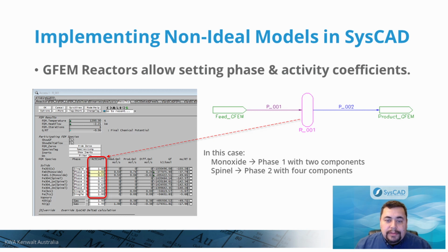We found also that it was not necessary to use solution models for iron BCC or iron FCC phases, as the possibility for oxygen solubility in the metallic phases was negligible at these temperatures, and no other impurities were considered in this model.